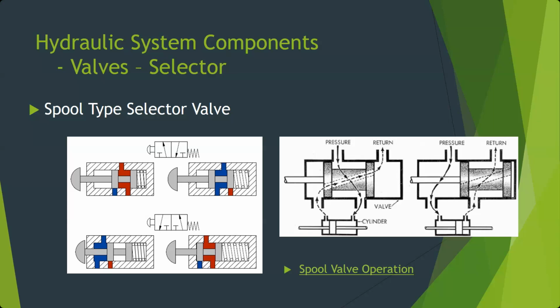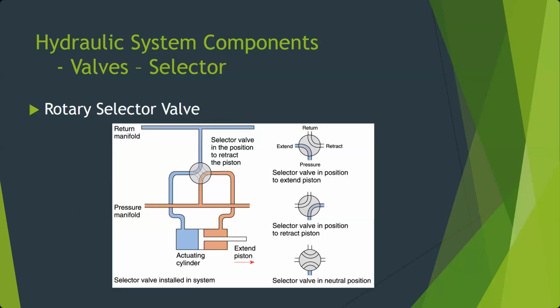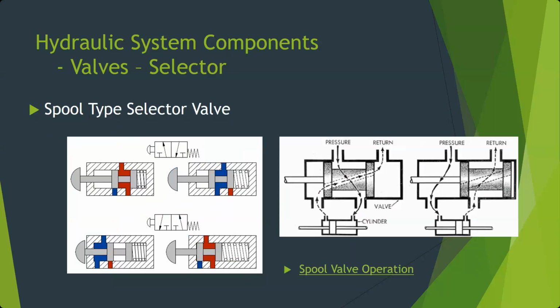In our earlier diagram, we had to have a way for two things to open and close simultaneously with our rotary valve. That's what's being shown here on the right side as well. So if we have a spool and they put a passage through the middle of it, now we can use that same spool valve to operate a cylinder in two different directions.